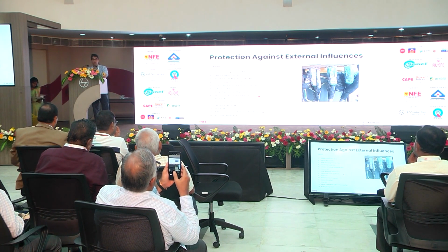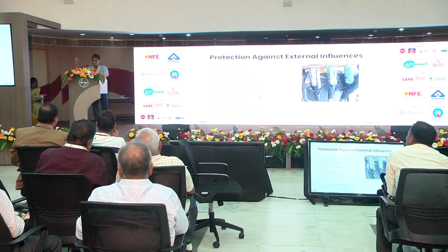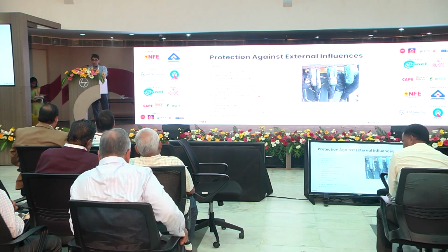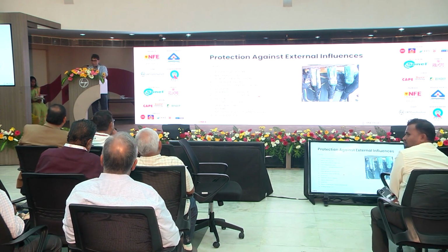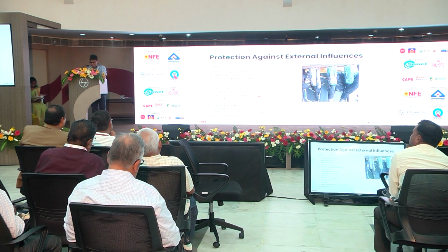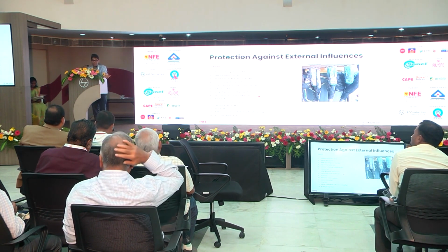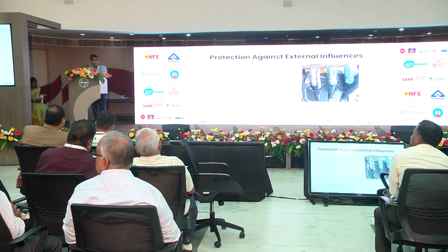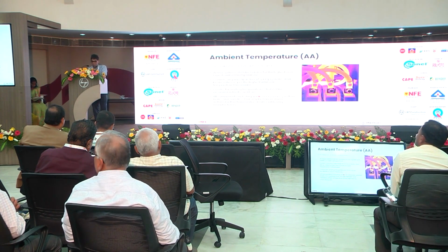You don't want to have to keep going back to the same installation again and again and performing maintenance work. I mean, I don't know about you guys, I really hate doing that. Maybe it's a source of constant revenue, but at the end of the day, the client is going to break their head and be like, why do you have to keep coming out to my installation? Can't you get it right the first time? RCD tripping is also very often caused by water getting into the cable and containment. If this is looked at, that can be greatly minimized. So let's look at these.